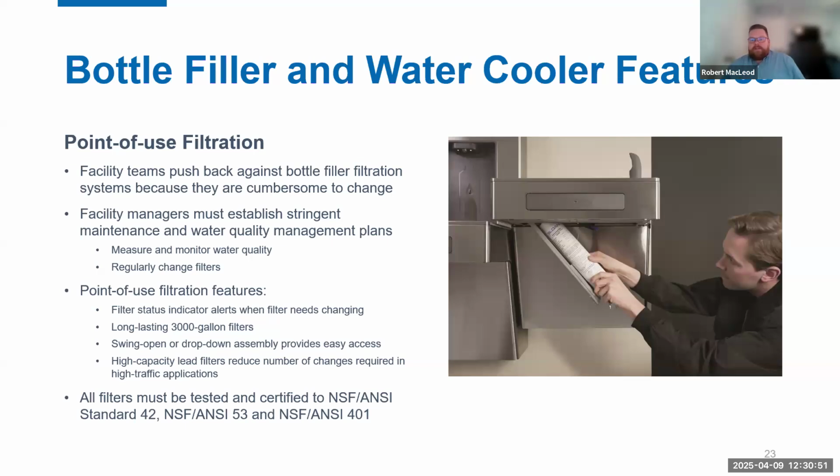But again, for that high capacity lead removal filter, in high traffic areas, you're going to have to change it a little more often. They should all make sure that they're certified to NSF and ANSI standards 42, 53, and 401 to ensure you're providing users with safer, cleaner, and better tasting water.